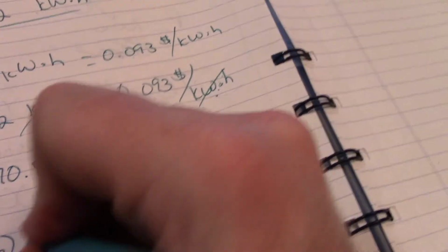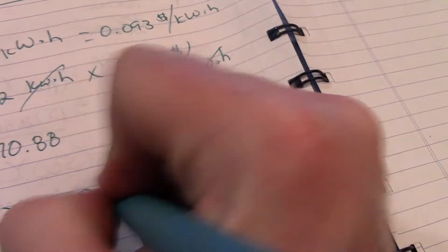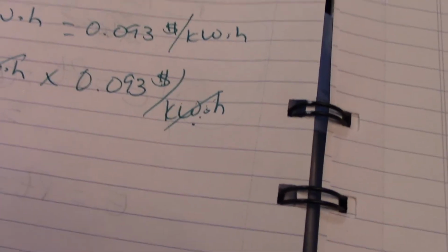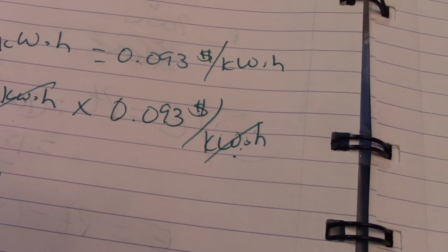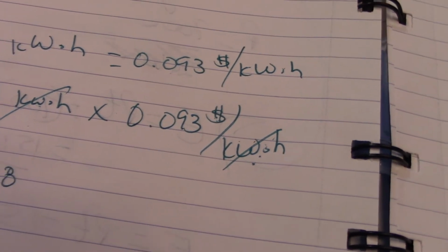Each speaker has a resistance of 8 ohms. So there's two speakers, and they're connected in parallel.